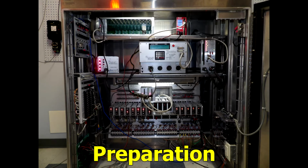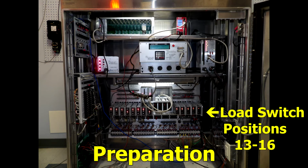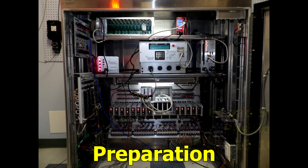Preparation. Before starting, you will need to determine which load switches are used to power the PED heads. In this cabinet, the load switch positions are 13 through 16. You will also need to determine which detector BIUs are available for use. In this cabinet, detector BIU number 1 is already used, so we can assign BIU 2, 3, or 4.